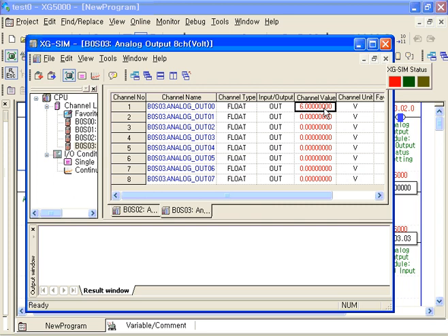That's for analog. So essentially you're trying to calibrate, you can actually force mid-scale. With 0 to 10 volts, you can force 5 volts on it. Yes. And you know that it has to be mid. Absolutely. Plus, if you're doing simulation,